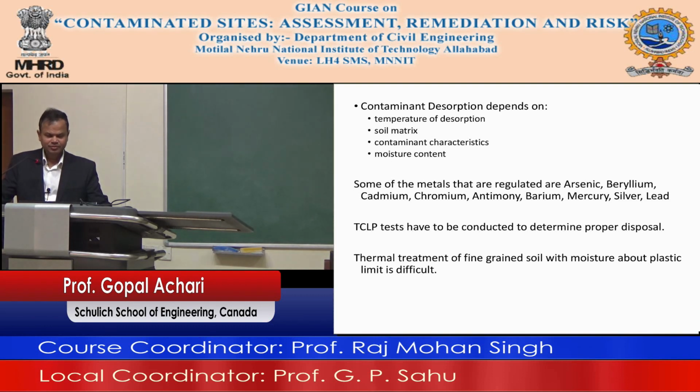After you have desorbed it, you may have to do the toxicity characteristic leaching procedure test to determine proper disposal. And as we talked about, thermal treatment of fine-grained soils like clays and so on, with moisture above the plastic limit is difficult, which means the soil has got lots of moisture in it. It is not easy to do that.